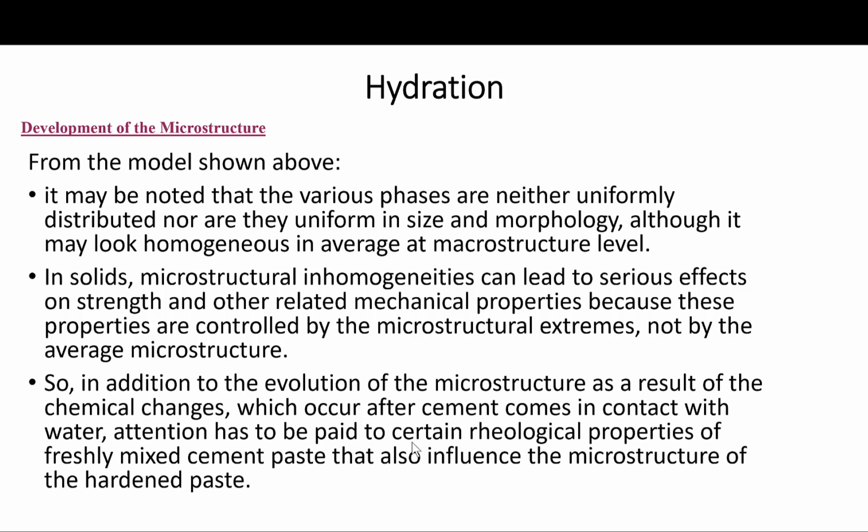These are examples that will help the rheological properties and remove calcium hydroxide from the microstructure, which would be harmful, as we discussed previously. Also, well-balanced aluminate sulfate ratios will ensure that hydration products susceptible to sulfate attack are not present. So basically, the densely packed microstructure will improve its durability.